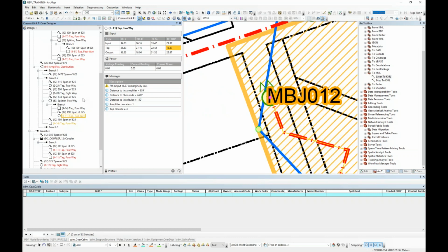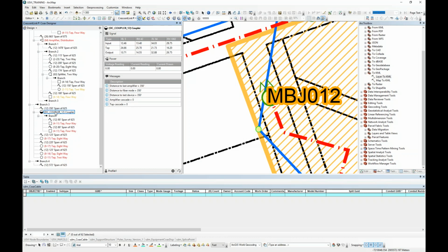Okay for that area and for the signal it's currently carrying, but some of these, because the amplifier settings were not correct as they should be, it's going to give you an error and say equalizer cannot be determined, the input signal is too low, 4-way tap, the output is too low, you're going to lose this. It should have an 8 dB tap. Let's see, we'll move a coupler, see what happens.